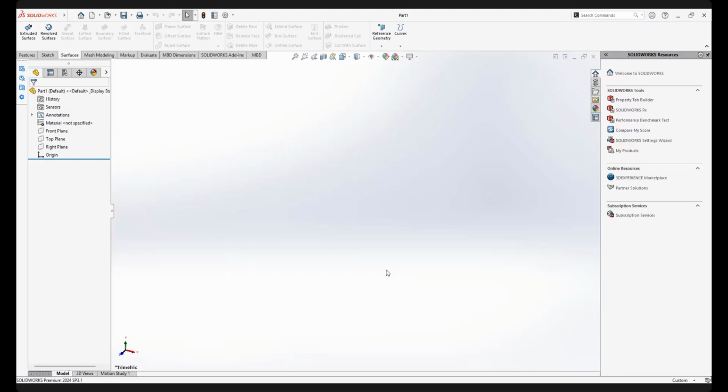So do not worry. Sometimes you can do exterior modeling first, then after that you make the main modeling. Okay, I'm doing the color black, the handle. I already took the measurement, so I do a cylindrical body. Make sure this one is millimeter. When you do product modeling, the orientation of that handle is standing up, so be careful about it. Later you can ask me if you don't understand. I will do it at the front plane, and I will do extrude because I have a cylinder.